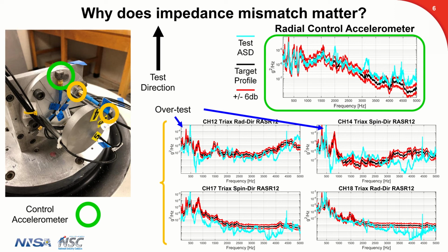If we get to higher frequencies, it begins to break down because there are resonances in the fixturing and everything that cause the controller some heartache. So we'd have to notch those out or do something there. But in this lower frequency range, it works well. But notice what happens if you look at other points on the test and how they compare to flight.